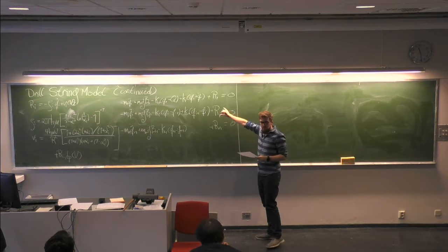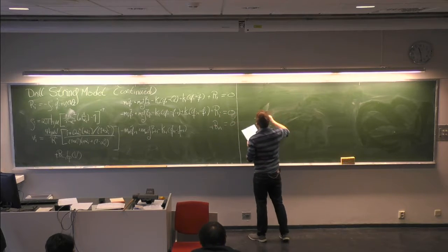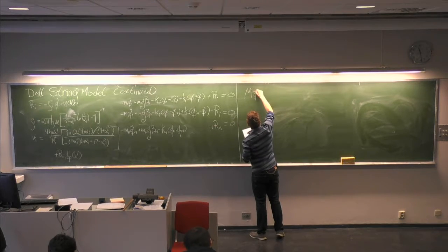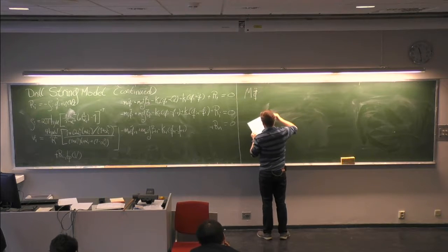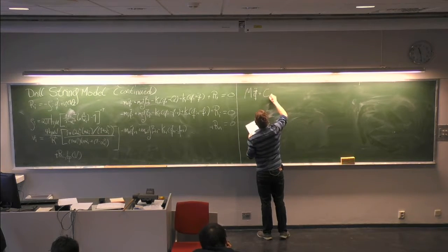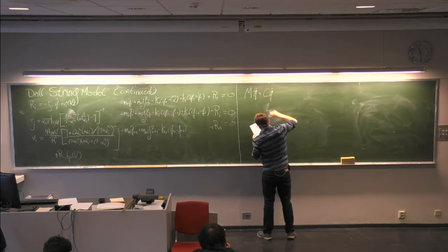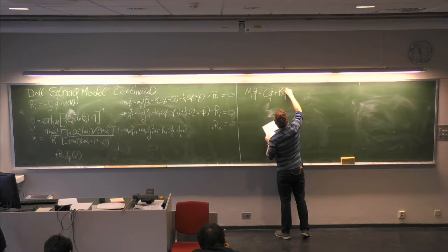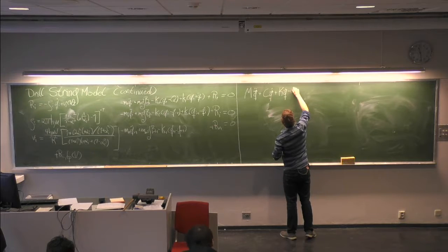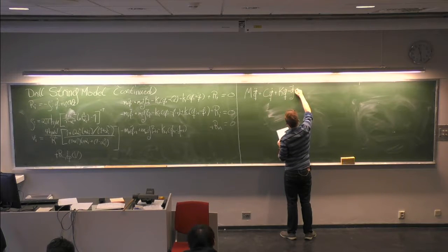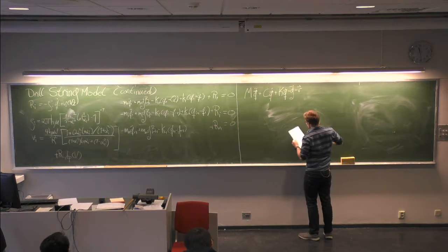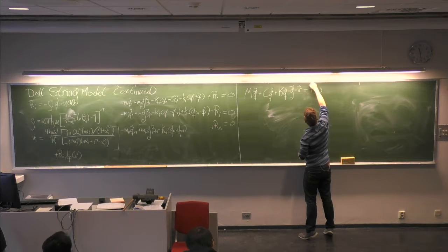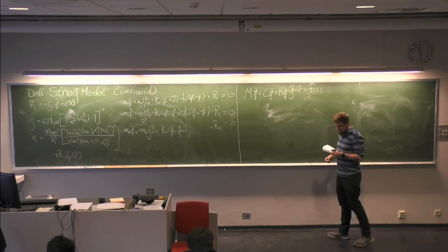Okay, so this system here can be written as big M, a matrix, times the displacement vector, or acceleration vector, I suppose, plus C times the speed vector, and I'll define all of these matrices. Plus K, plus G matrix times vector V, equals some kind of driving force vector, a function of t.